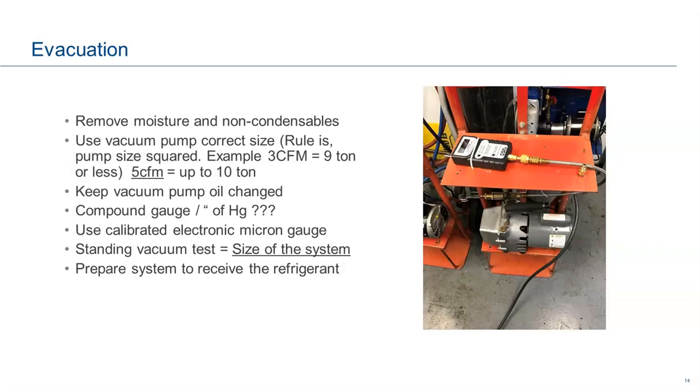I know on a typical residential system, when I first got started in the industry, I would pull it down and let it stand for like 45 minutes or an hour. Just enough time to maybe clean the job site up or go to lunch, or take lunch there in the truck. And then we need to prepare the system to receive our charge, okay?